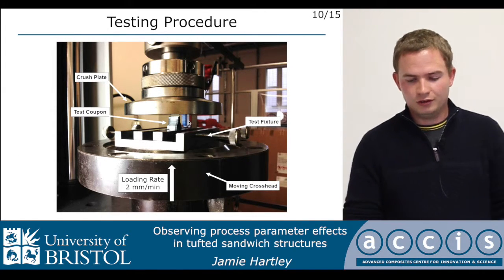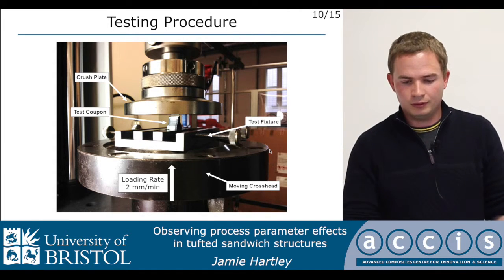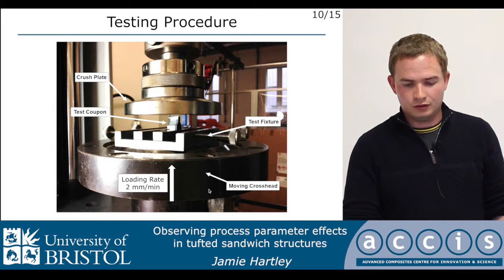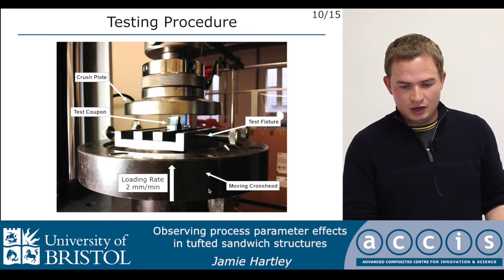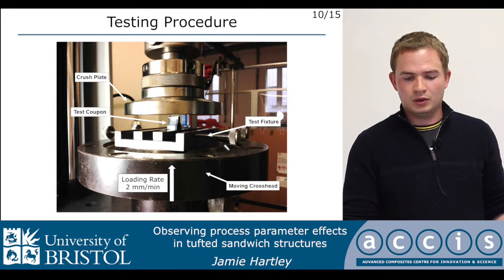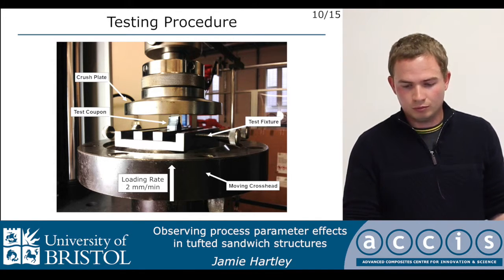So the actual test procedure was carried out in the labs at the University of Bristol. It's carried out at a very slow, quasi-static loading rate of 2 millimeters per minute, which is basically being used to validate this process before it would ever be carried out as a dynamic test, which is obviously more suited to the automotive industry.